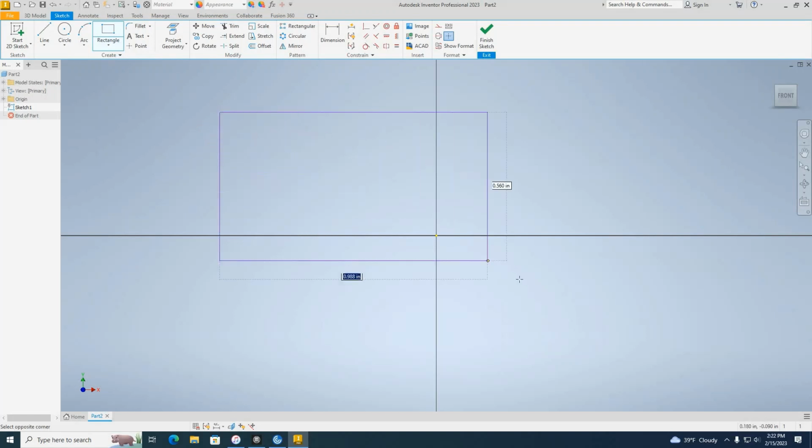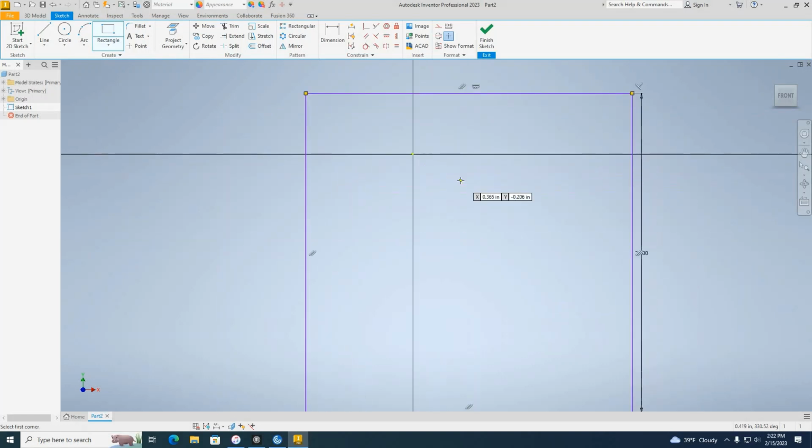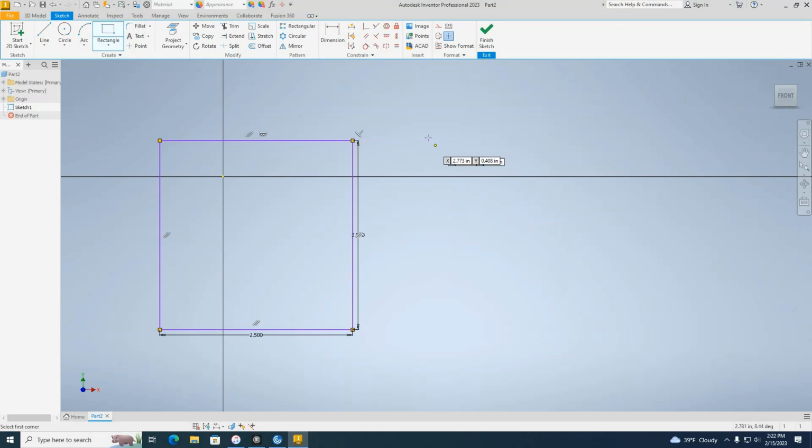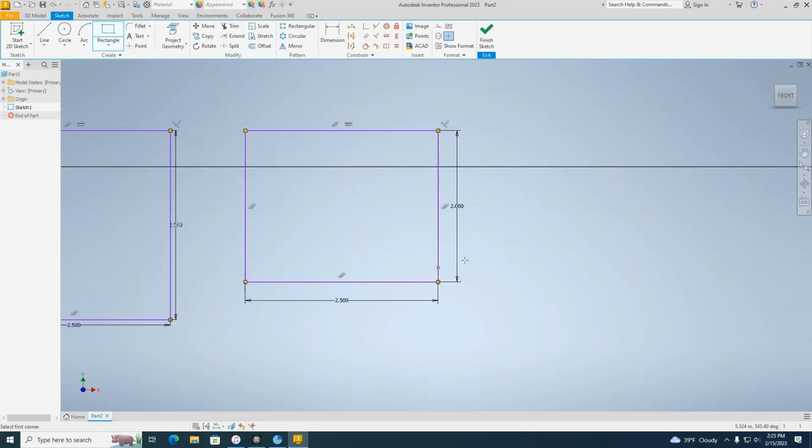And to draw a square, you're just going to click and start stretching your mouse down to a corner. And I like to keep my keychains around 2.5 inches. It's not so bulky then. It seems to be a pretty good size. So we're going to go 2.5 on the keyboard, click Tab, 2.5, and Enter. And that's going to get you a 2.5 by 2.5 square. You can also do rectangles by just changing those dimensions around a little bit. So you go like 2.5, Tab 2, and you could have more of a rectangular shape.